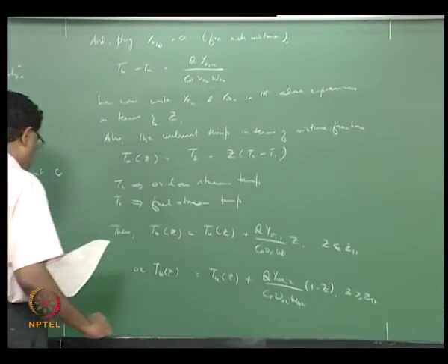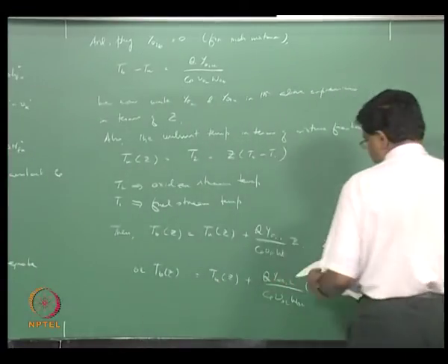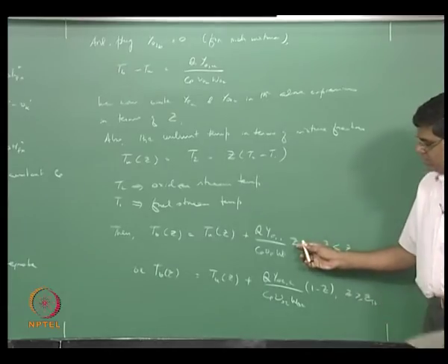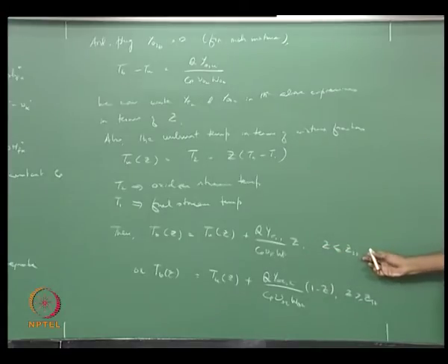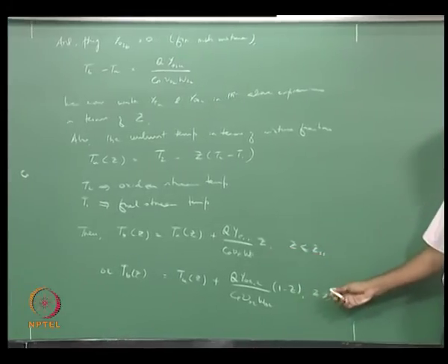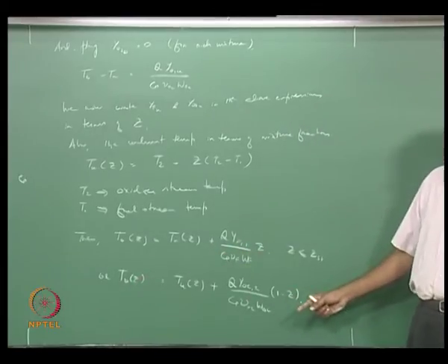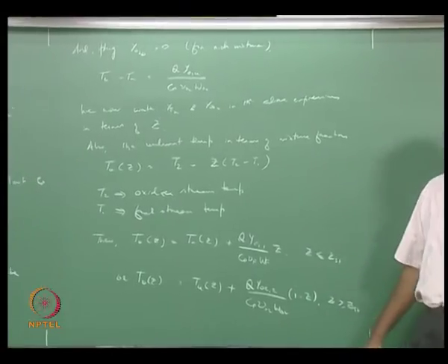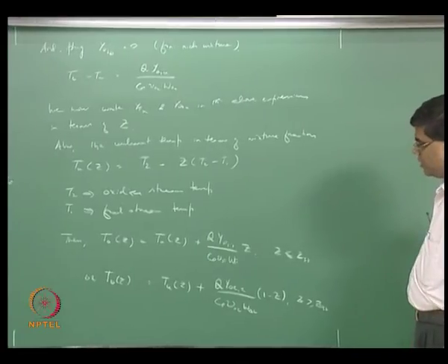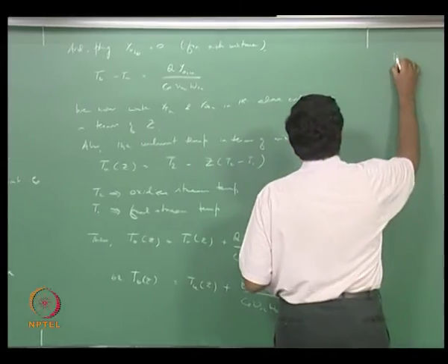Right. Now you can calculate the maximum temperature. As Z keeps on increasing, you see Tb will keep on increasing up to ZST, and when you cross ZST, you have to use this expression where, as Z keeps on increasing, Tb keeps on decreasing. At Z equal to ZST you should get the same expression from both. That means you should have one temperature at which the stoichiometric mixture has a burn temperature. So that will be the maximum temperature.